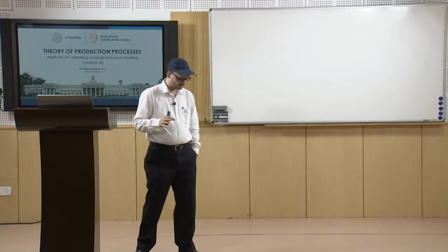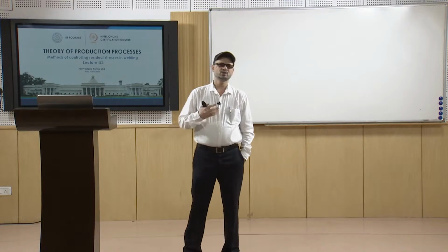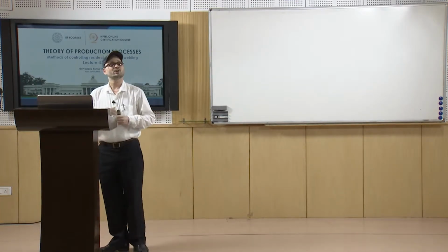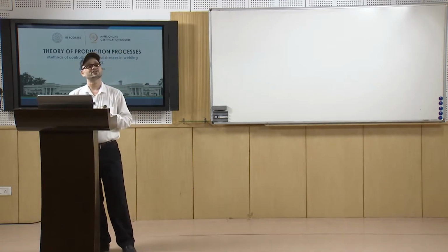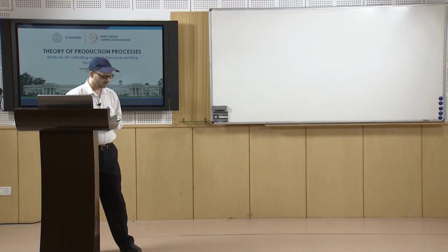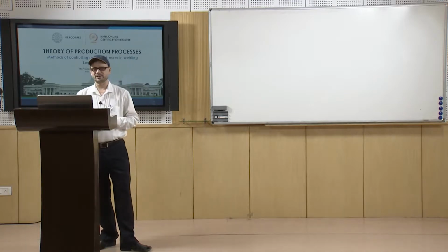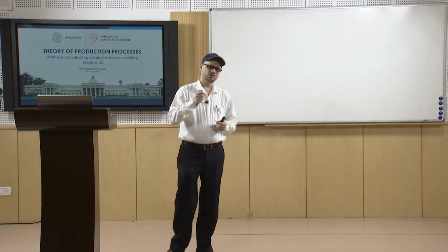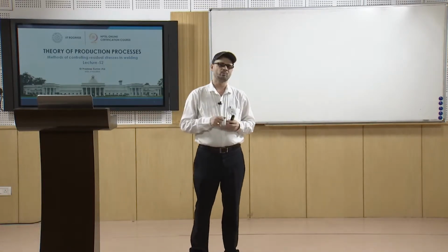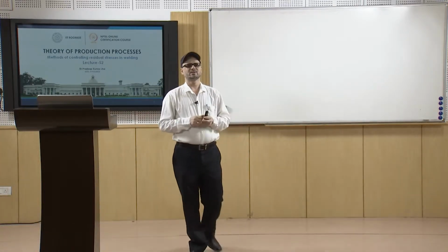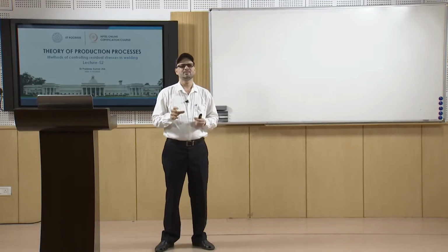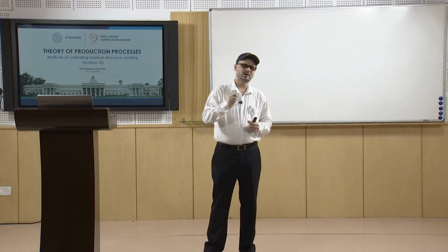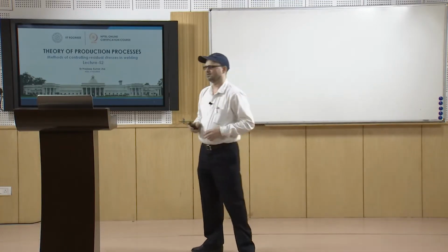So, these are the methods which are basically used for removing or reducing the residual stresses in welding. Now, peening, what is peening? Peening means you are having repeated blows with a hammer or a mechanical hammer, you are putting the blows on the weld.